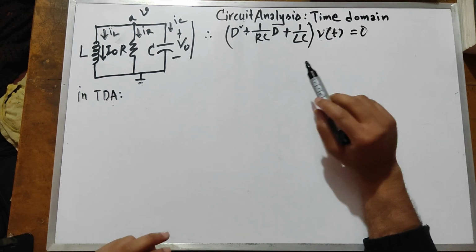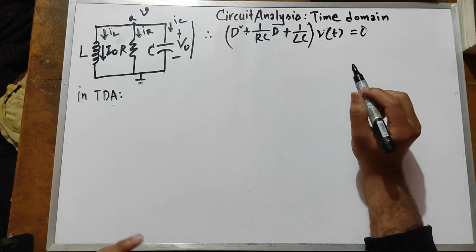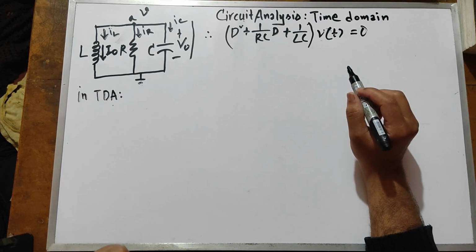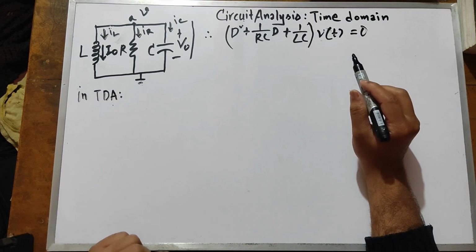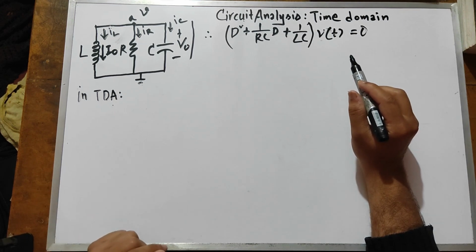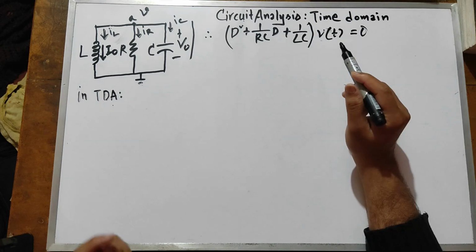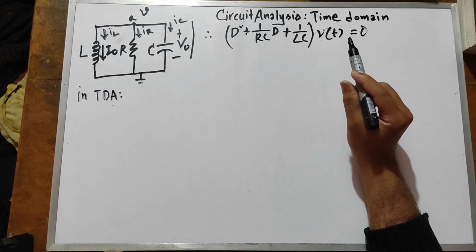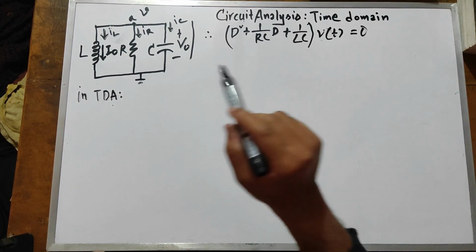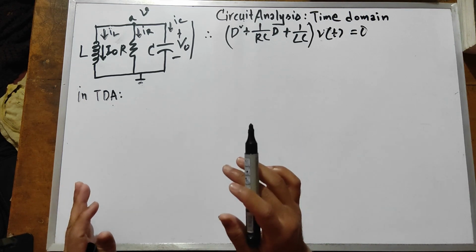You know that the general solution or complete solution of a differential equation has two parts, one is the complementary solution and the other is the particular integral. Because the system has no input, there is no particular integral, and as a result the circuit has no steady state response. In terms of system response, this complementary solution is the transient response of a system. So we are only gonna find the transient response for the source free circuit.